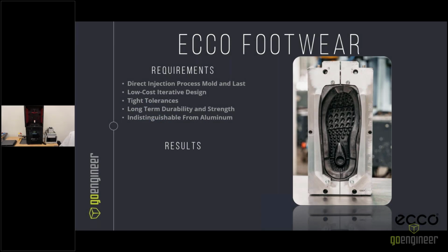Echo Footwear, they are based out of Europe. They had the intention of printing the mold and last to be used in a direct injection process. What a direct injection process consists of is directly shooting the sole, the polyurethane sole, into the midsole. This eliminates any stitching and further assembly, reducing assembly cost, and also increasing the lifespan of the material.